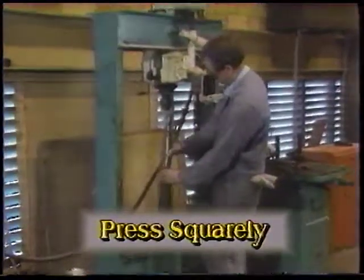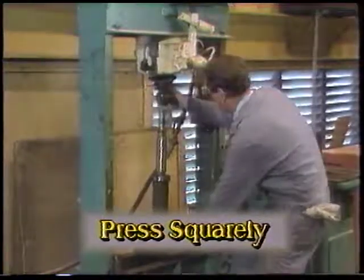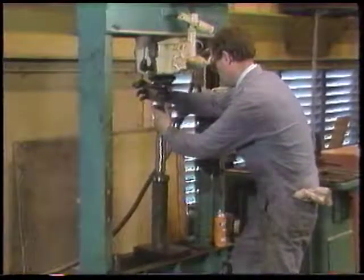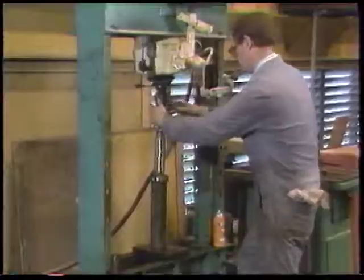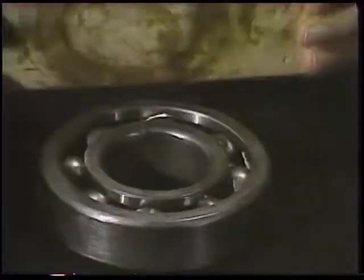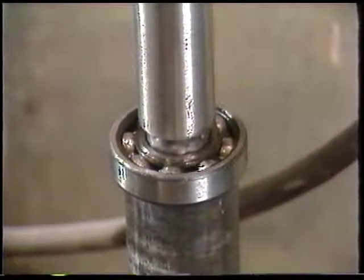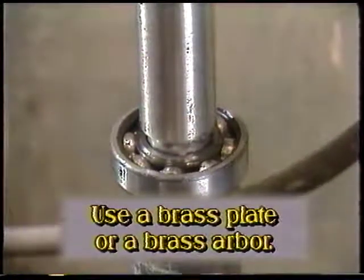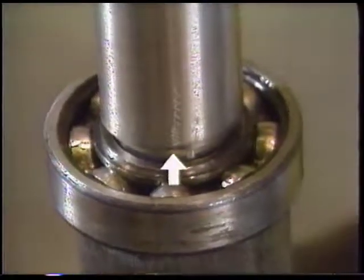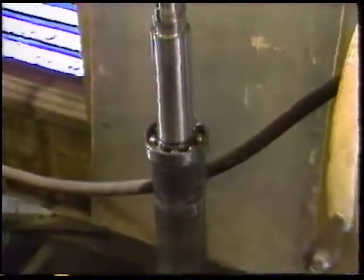Press squarely. The press must be arranged to push the bearing on the shaft or into the bore absolutely straight. The ram must be lined up precisely with the shaft or the bore, and the force must be equal around the full circumference of the ring. Do not attempt to press with a wood block or any material that can compress unevenly or leave chips or splinters in the bearing. A brass plate or brass arbor is preferred, since brass is soft enough not to damage the surfaces of the bearing, but hard enough to push on the bearing accurately. Usually, there is a flange or shoulder that presses against the bearing to ensure that the bearing is positioned correctly.